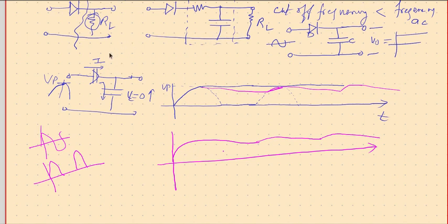So, what are we doing? Here we are rectifying, and we have been using only half of the cycle. So this is called a half wave rectifier, and we are going to have one more rectifier called the full wave rectifier, which converts both cycles into positive, and thereby these undulations can be further minimized. And that's what we are going to see in our next session.